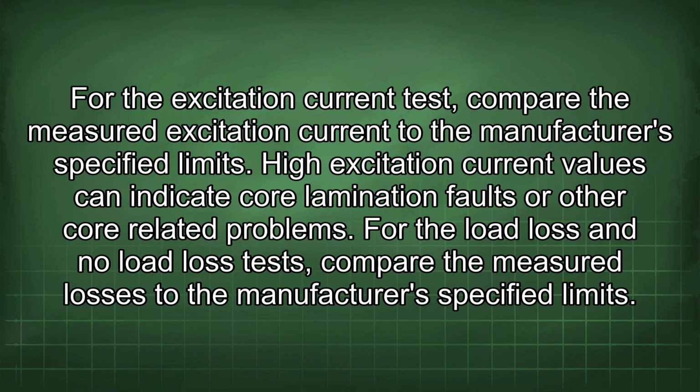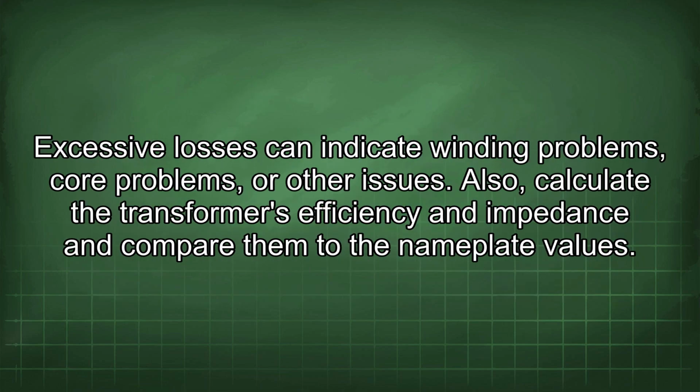For the load loss and no load loss tests, compare the measured losses to the manufacturer's specified limits. Excessive losses can indicate winding problems, core problems, or other issues. Also, calculate the transformer's efficiency and impedance and compare them to the nameplate values.